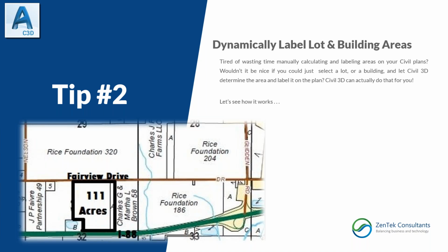It's one thing with parcels, if you take the time to do that, some of us do, some of us don't. I still see a lot of folks going in, drawing polylines, doing calculations, listing an area and manually typing it out with mtext. Again, using basic label styles, you can easily label the areas of just two-dimensional polylines, whether it's lot lines or buildings, in just a few clicks of the mouse. It's all about creating a label style for yourself.